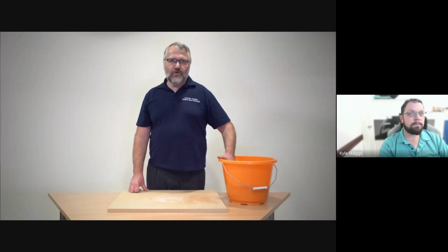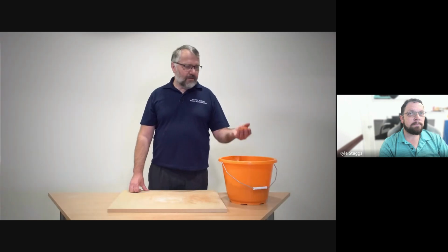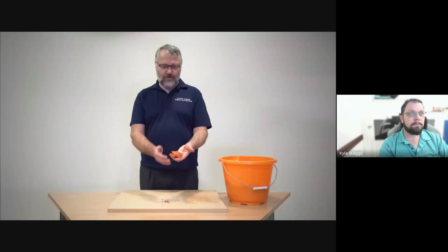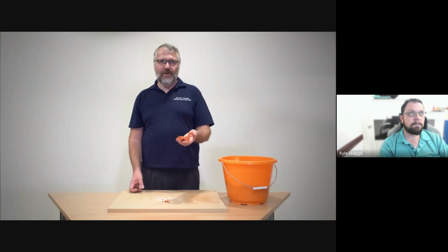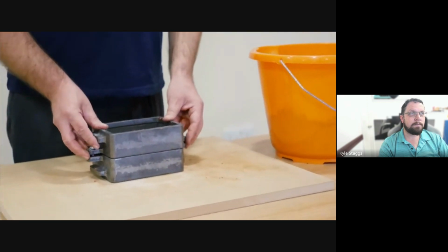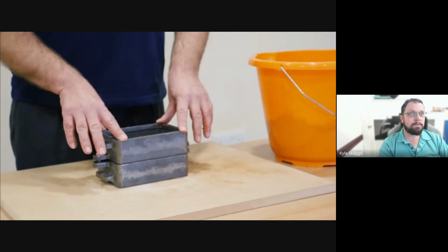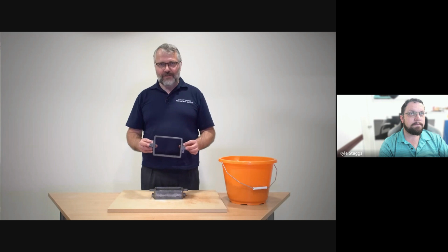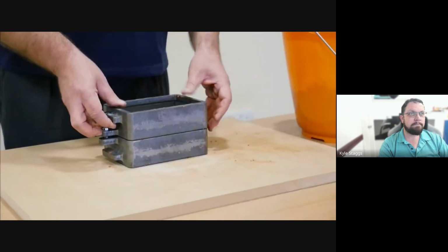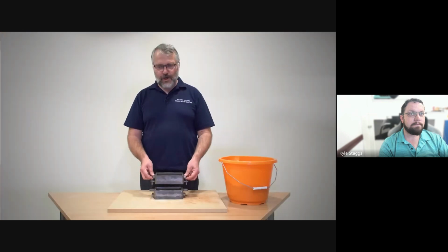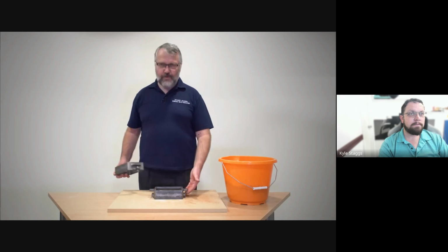Rather than using water to bind the sand together, this sand is bound with oil so that it will bind together and hold a shape really well. Using oil means that we can use a finer grade of sand, which will give a better quality of casting. We're going to make our sand mould in a metal box known as a flask. This is a two-part box which has locating pins so that they can be taken apart and locate accurately each time. The top is known as the cope, the bottom is known as the drag.